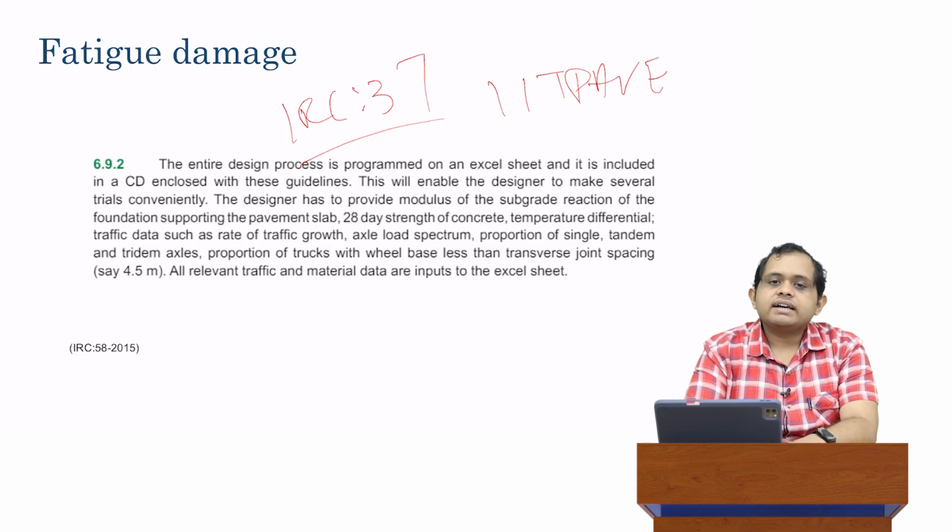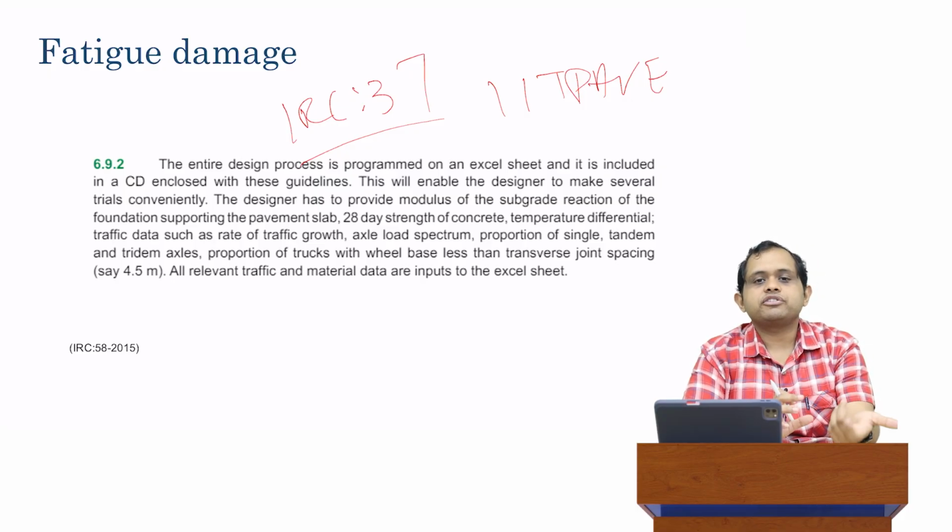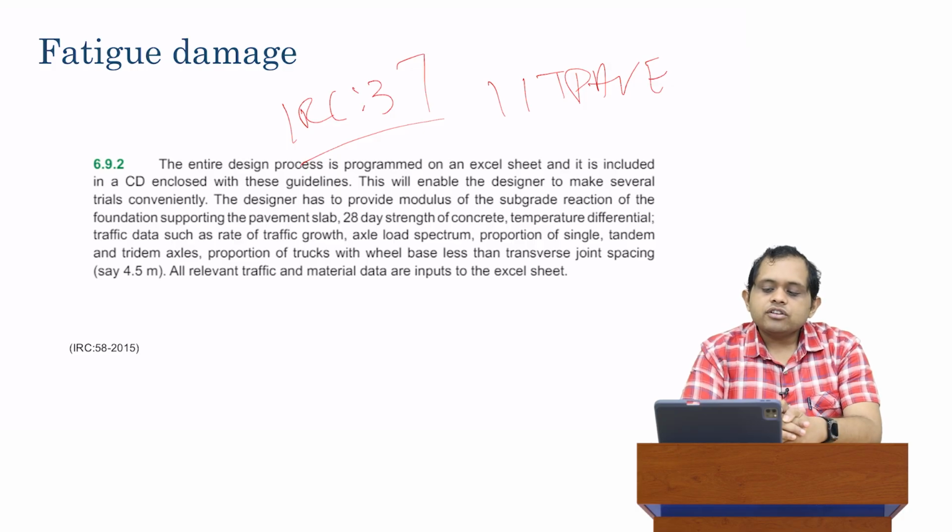And IIT Pave is a layered elastic analysis software that can calculate deflections, strains and stresses, but mainly it is used to calculate strains in IRC 37. There is no such companion software provided by IRC 58. Instead, there's actually an Excel sheet which has been included.